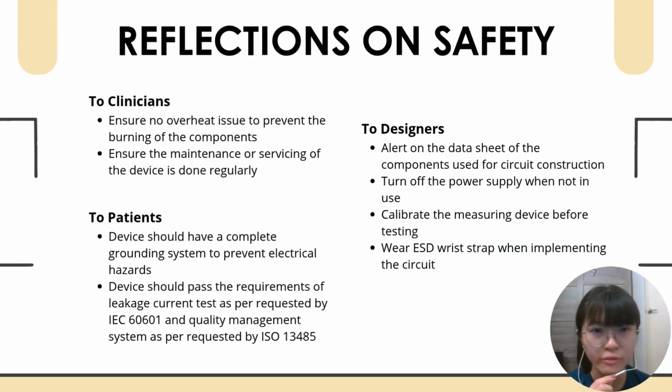Safety is very important for those who develop or operate medical devices with amplifiers. For clinicians, there should be no overheating issue, to prevent the burning of the components, and the maintenance or servicing of the device should be done regularly. For patients, the device should have a complete grounding system to prevent electrical hazards, and it should pass the leakage current test as required by IEC 60601 and the quality management system as required by ISO 13485.